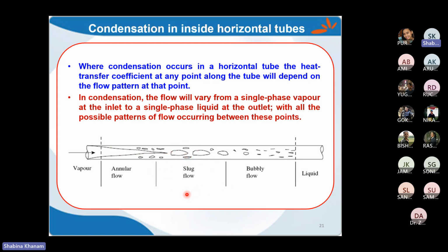Okay, and if the bubble size is large enough, it will move, so it will create vibration in the tubes because of the size of this bubble. But baffles and everything is there, so we don't need to worry about that. But if you are considering a single tube, this type of slug flow will be there.